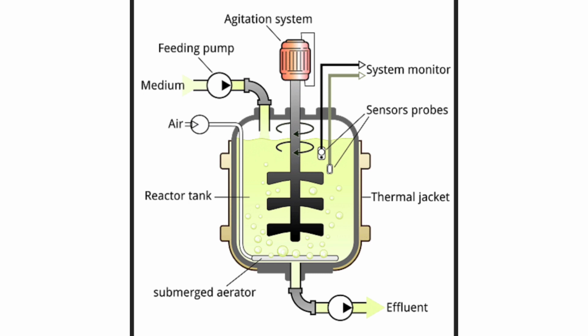Bioreactors. Any manufactured equipment or system that supports a biologically active environment is referred to as a bioreactor. The bioreactor approach is an ex situ biochemical processing system that utilizes microbes to remove contaminants from wastewater or pumped groundwater, as well as the solid and liquid slurry stages of contaminated soil treatment. This process might be aerobic or anaerobic in nature.